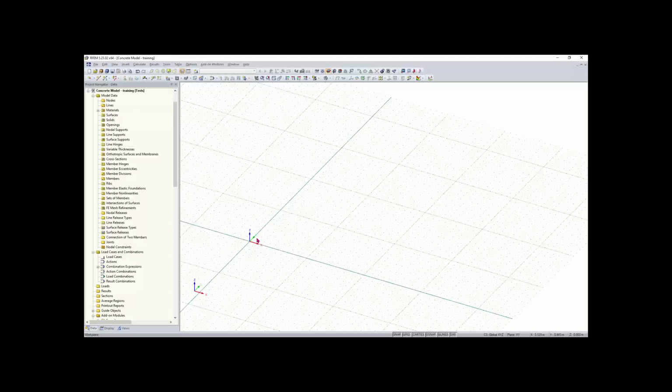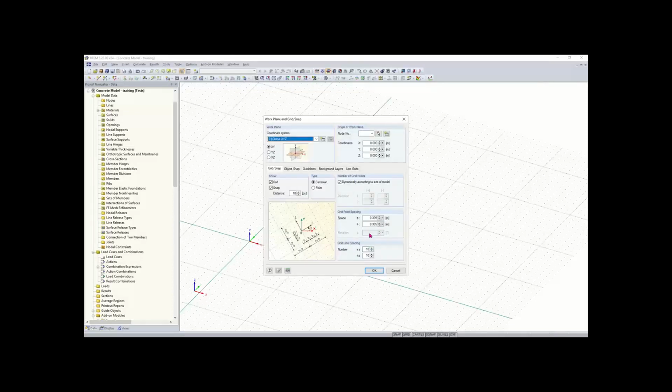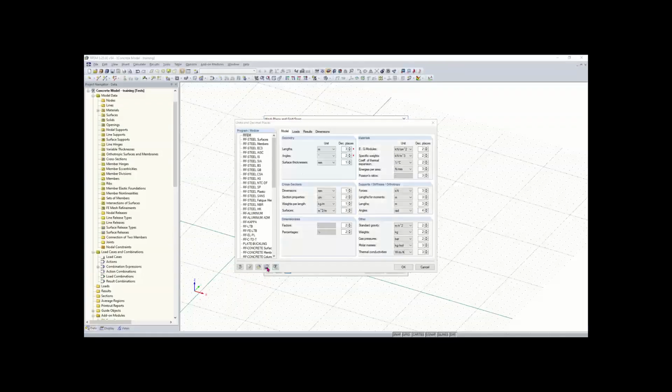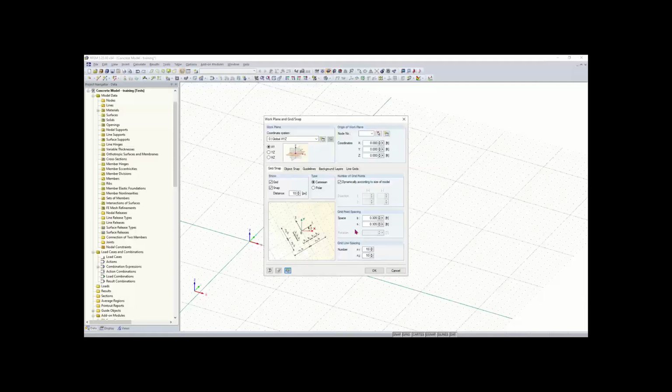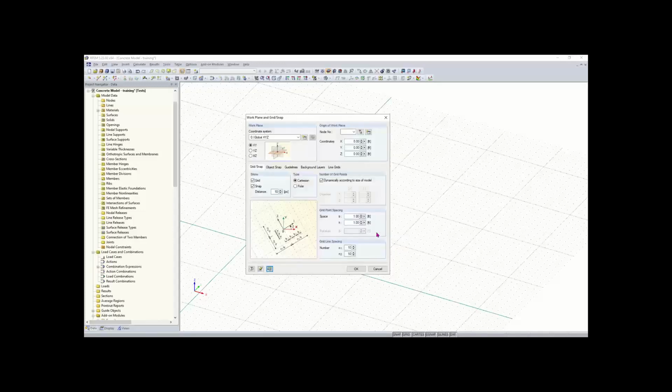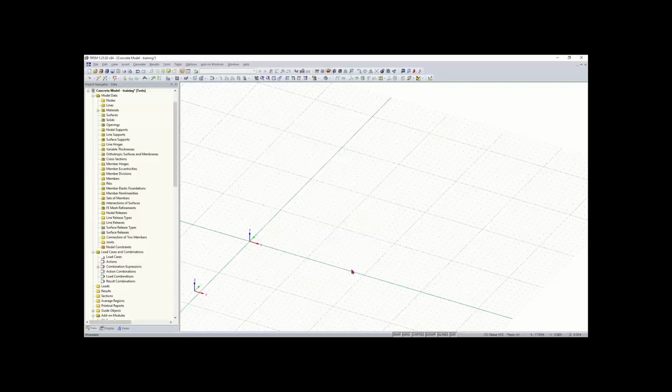So that changes automatically. I don't have to worry about expanding that at all. Also, my grid points are still 1 foot by 1 foot. Actually, I'm in metric right now. I think I might have set my program to default to metric in the beginning, so let's change that. We'll go to load save profile, and if you want to change the default of what your units are in, I'm going to check imperial, click OK, and then this button right here sets your default, so I'm going to set my default as imperial, click OK, and now you can see that my spacing should change to 1 foot by 1 foot. There we go. You can change the spacing of these grid points, but I'm going to leave them at the default of 1 foot by 1 foot.